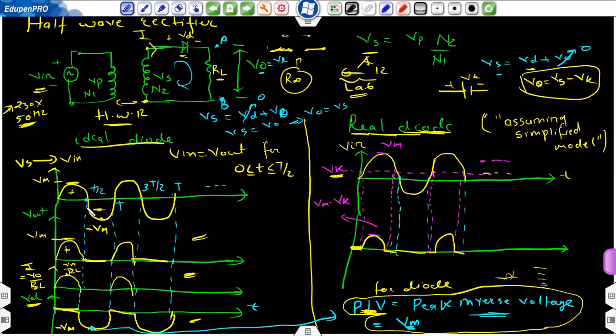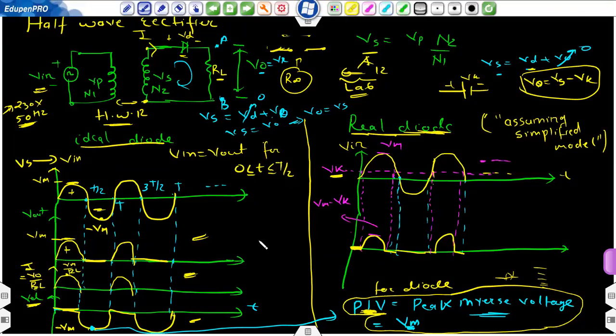So we need to first rectify this negative half. Then we have only the positive half. Then we will perform some more steps and convert it to a straight line like this. So it will only show the graph above the x-axis. Yes, exactly. And for the full wave, it will flip the bottom portion to the top portion of the x-axis. We will discuss the full wave in great detail.